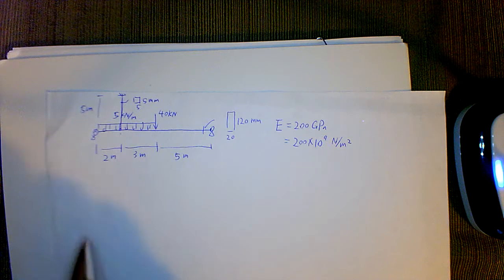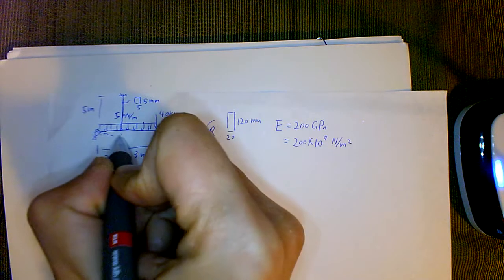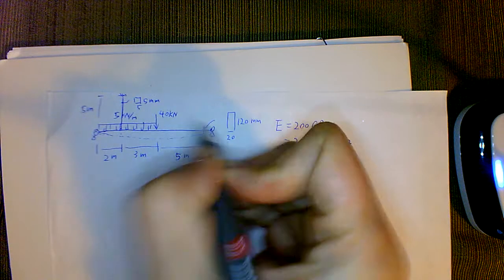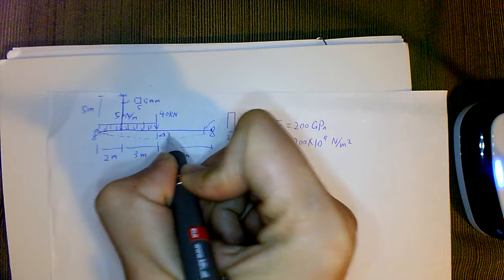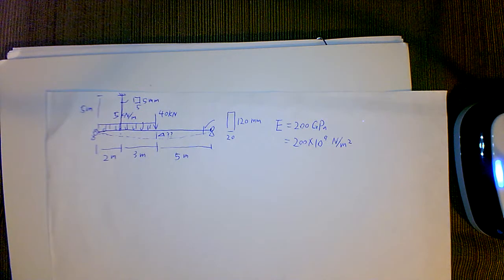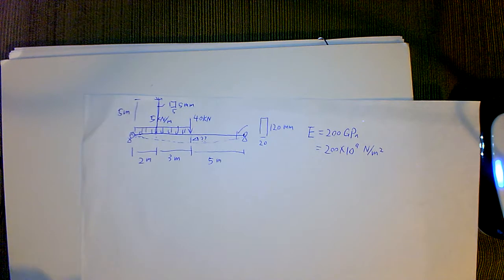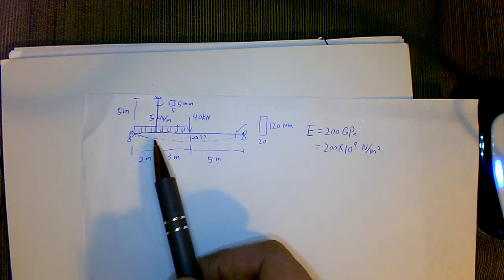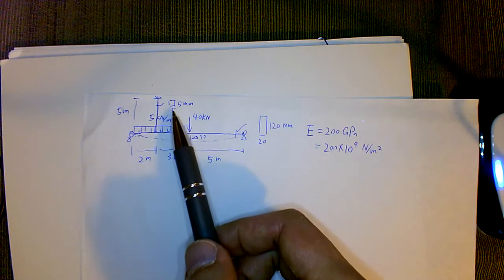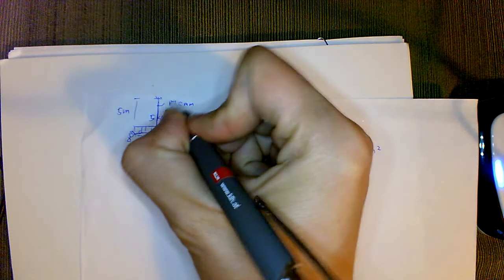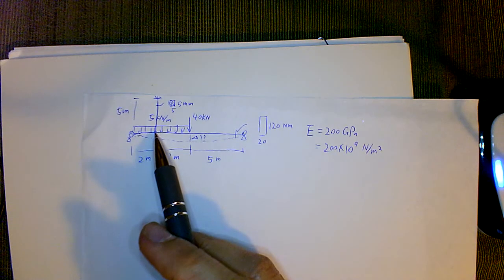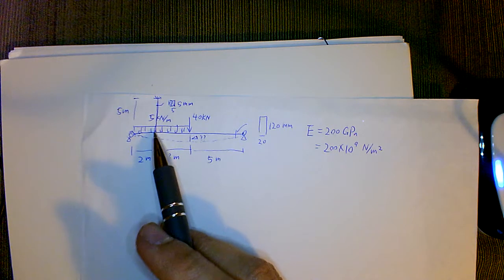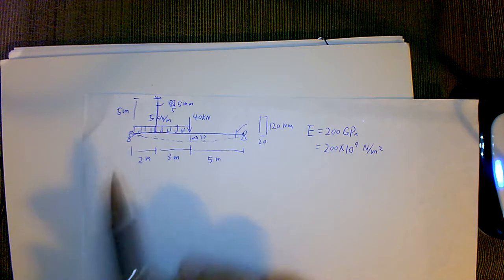Okay, and we know this thing is gonna somehow deform into this shape. And we want to find out what is the delta at mid-span. Okay, just think for a moment about how you're going to solve it. If it's the traditional way, you're like, oh, this is so much pain. It's indeterminate. And this cable, if you give me A and length, is like a spring, so there's some deformation compatibility here. I'm gonna dig out this force, do the compatibility and solve for everything. It's a pain.